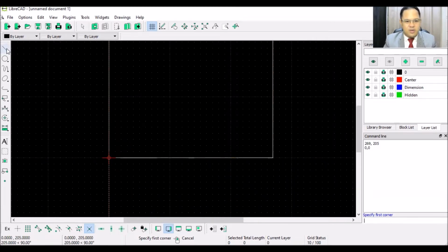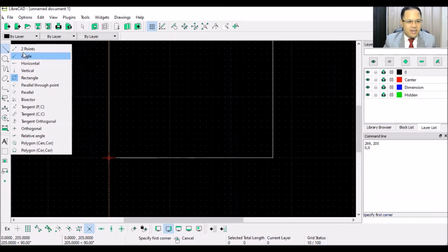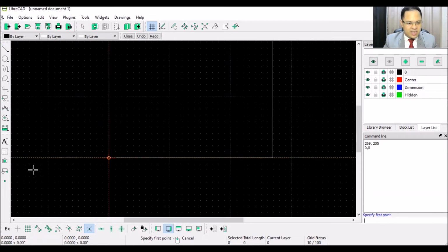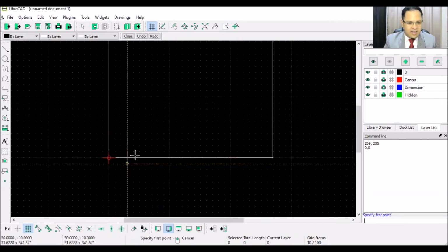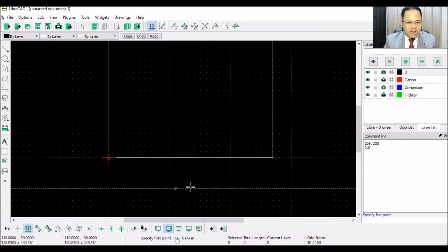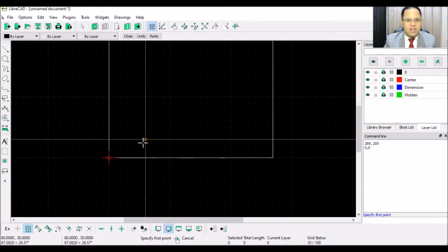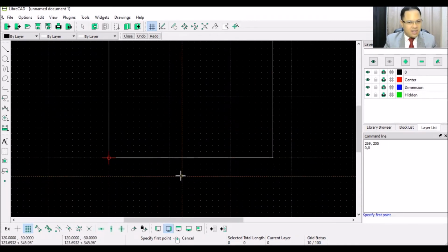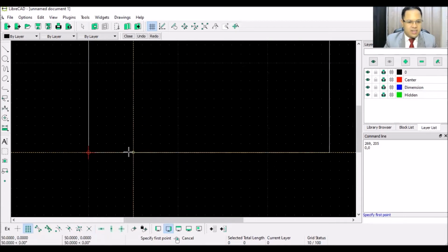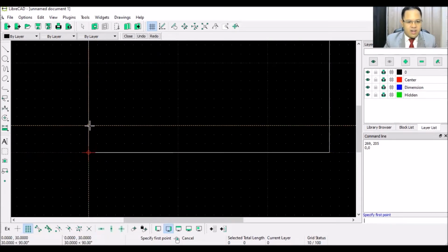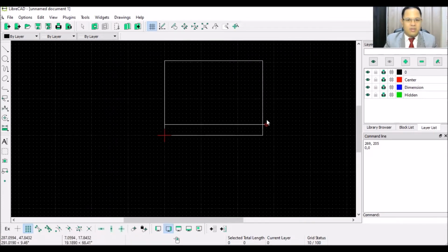Then I want you to select here 2 points and make sure that snap on grid is selected. Then in our drawing area, you can see their dots. Those dots serve as guidelines for our drawing. Okay, please count from the bottom. 1, 2, 3, 4. Okay, select it here and draw our line in the bottom part.